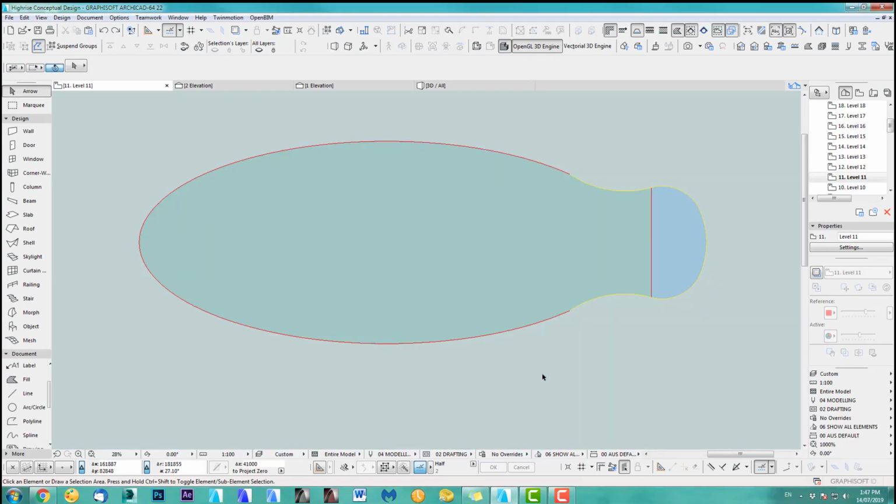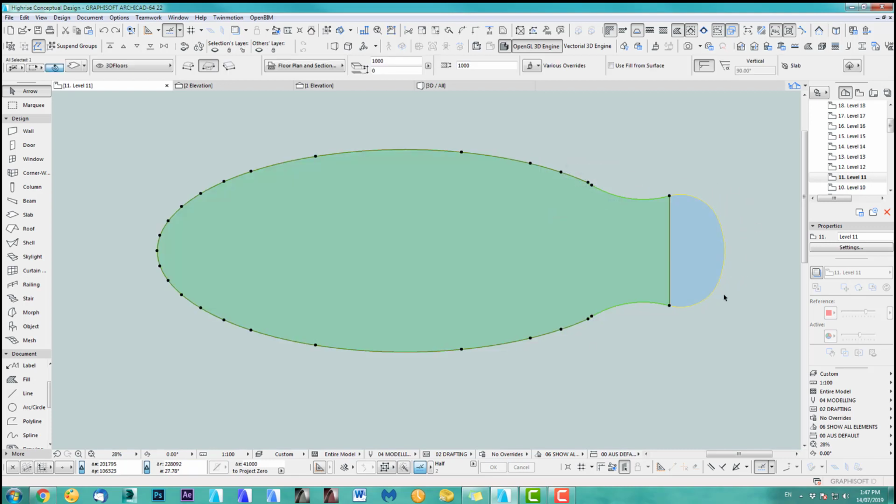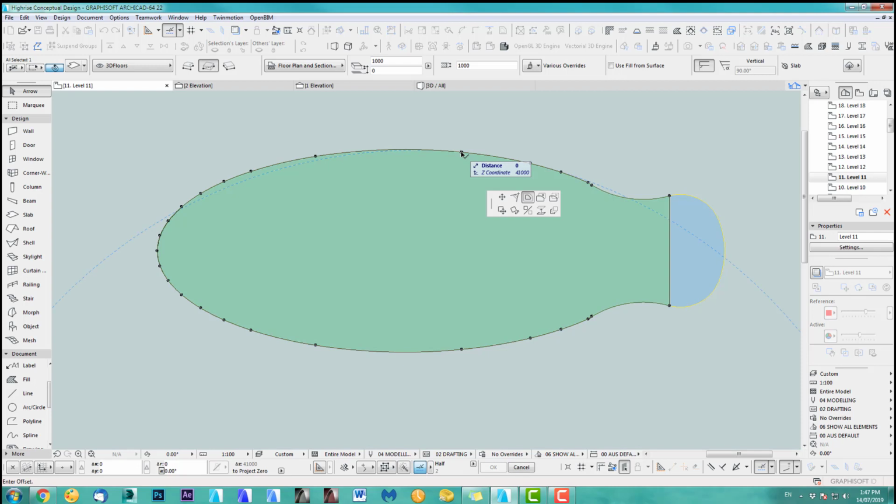Great. Okay, for the next 10 levels we do something different. We will reduce the whole plate with this offset tool here. As you can see, I can't go every 1 meter for 10 meters, 10 levels, as I can only go to about 8.7, and you see that's where the corner stops. So to make this a little bit round like this, I think 6 looks still good. So let's do 10 levels at 600 mil.